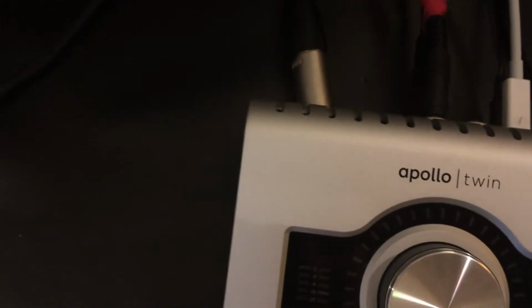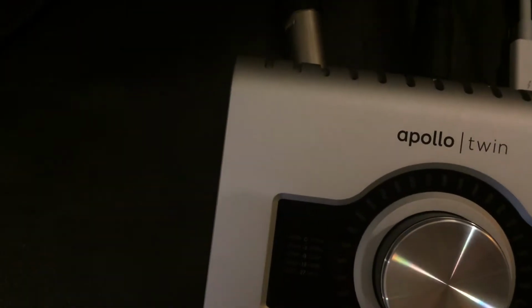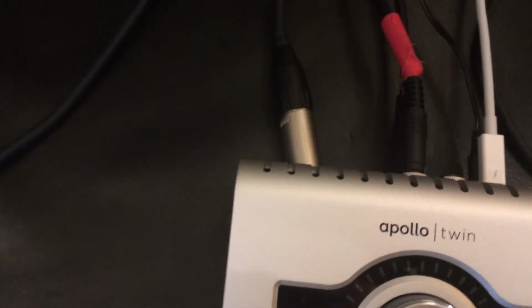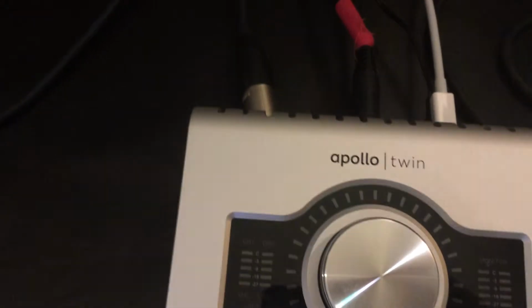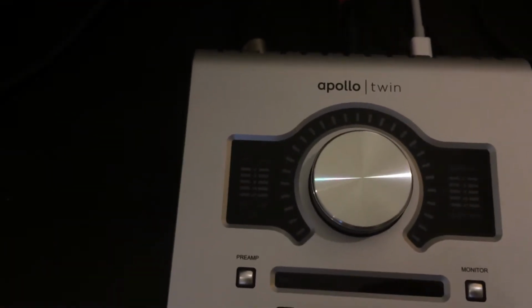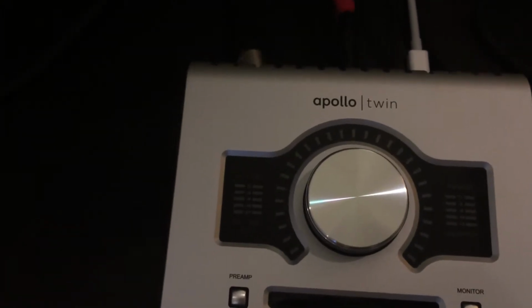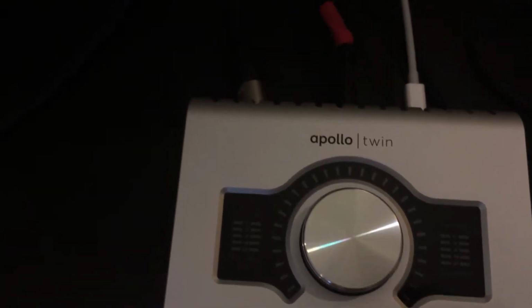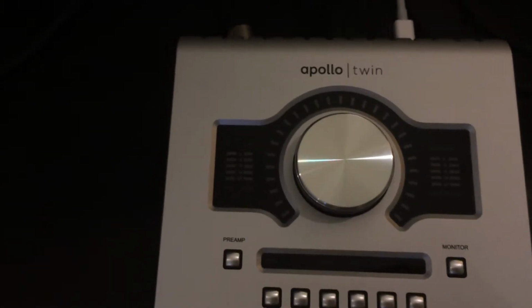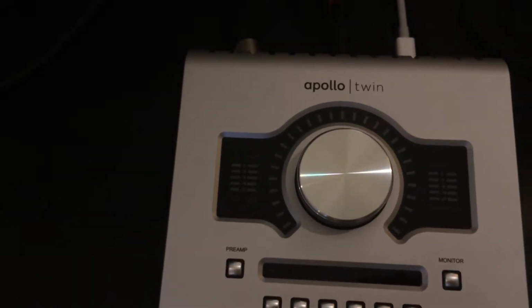The preamp is designed to boost the audio signal up to line level or standard operating level. There are many functions of the interface, but this is the first stop that it makes. After it exits the preamp, it goes into an analog to digital converter, which basically converts the analog signal into binary code, which is represented by ones and zeros.